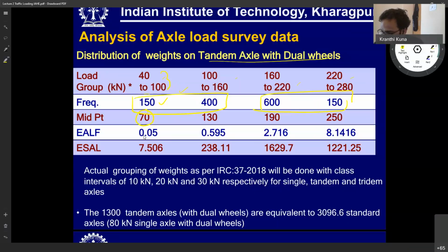So do we keep the factor of safety for these? I mean, like in the RC design, we keep a factor of safety. For the road design, do we keep the factor of safety? We do not have a factor of safety, but we have reliability factors, which I'll be discussing later when I'm discussing the performance equations. We do not directly have factors of safety, but we have reliability factors in performance, which I'll show you.